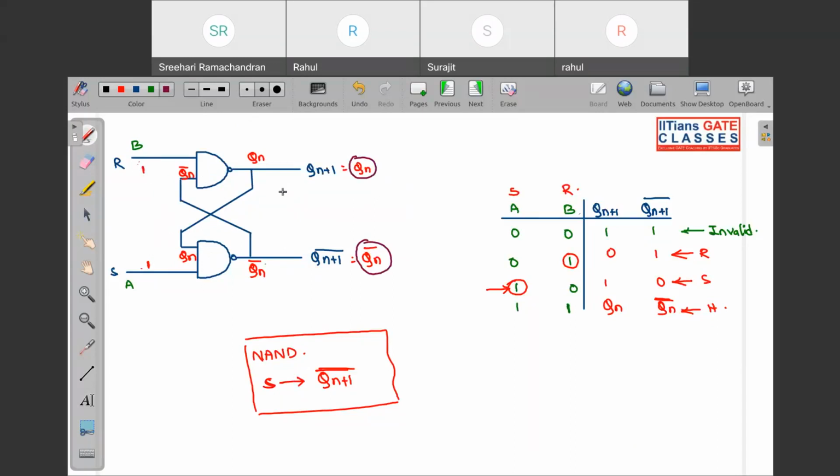Some of them might get input at a later stage due to propagation delay, or the concept of fan-in and fan-out. The inputs might come from gates with different propagation delays, so even if we have identical latches, output will not be produced at the same time.